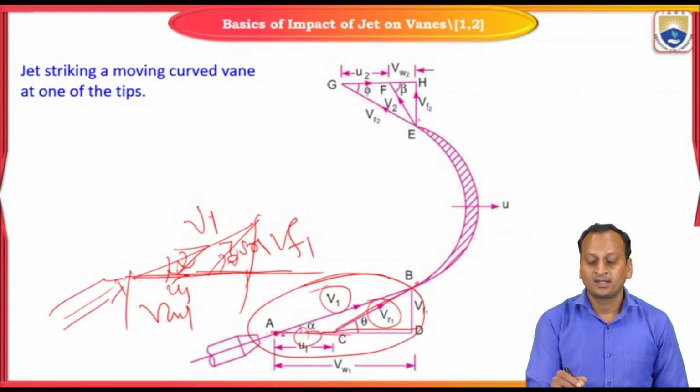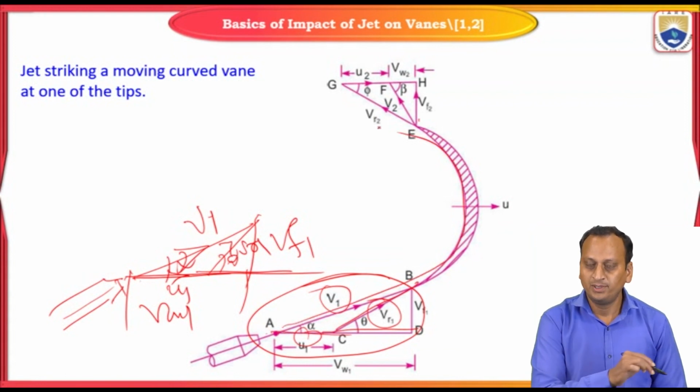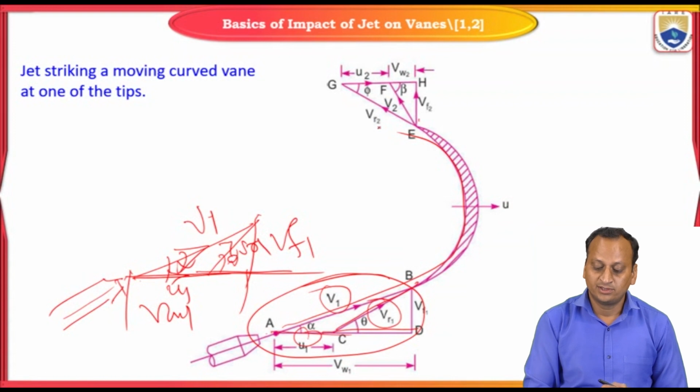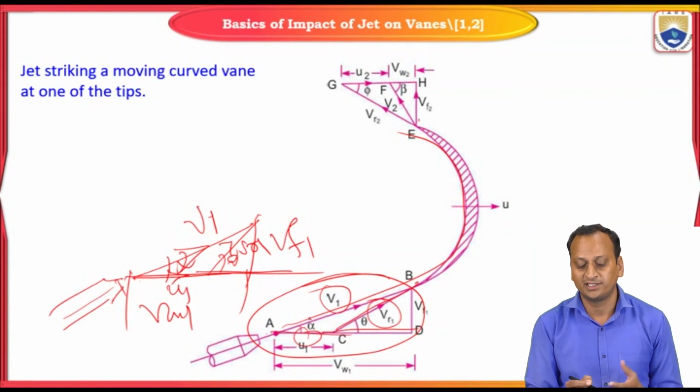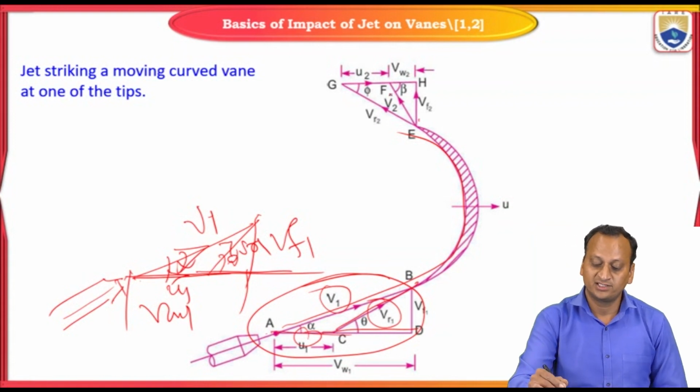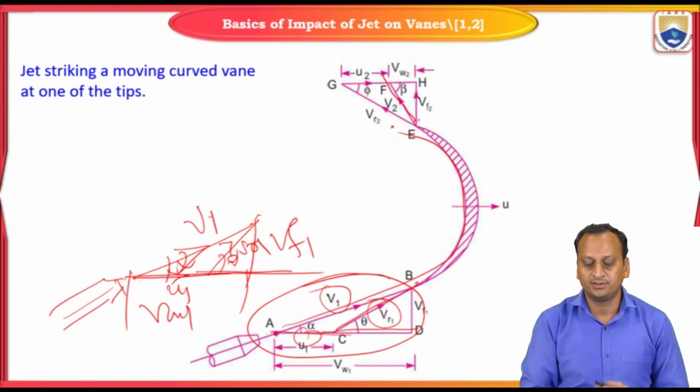After moving through the inner surface of the blade, the jet velocity V1 becomes V2. The same velocity cannot be obtained due to frictional losses. Therefore, the velocity will be reduced. The line will be plotted like this. So V2 is reduced due to losses.